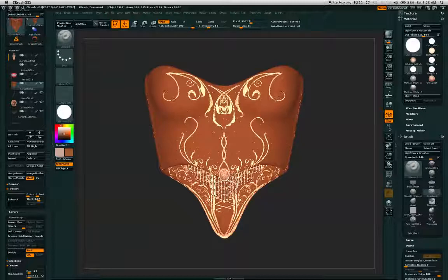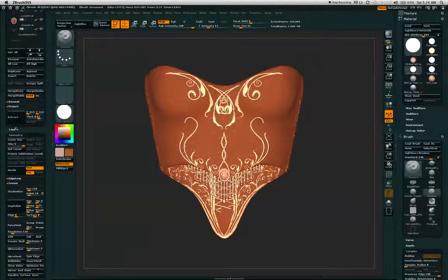Also use that for an area that you don't like the material or color. But as you can see, it leaves back behind the detailing that was left from the brush having Z add on. Simply take your smooth brush. I usually use the smooth crease brush. And erase or smooth out the details that were left behind.